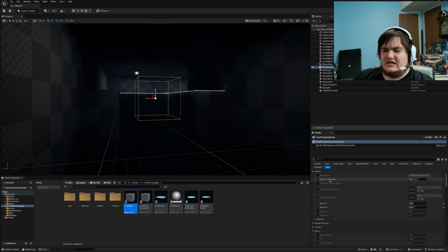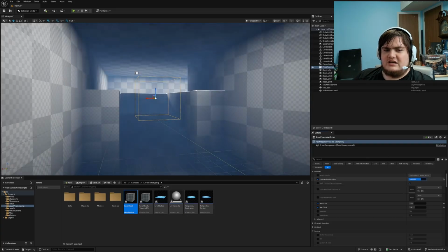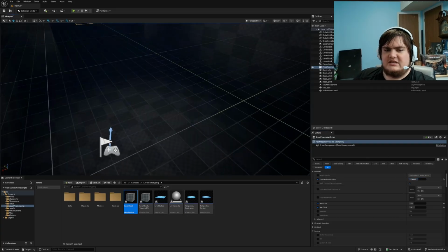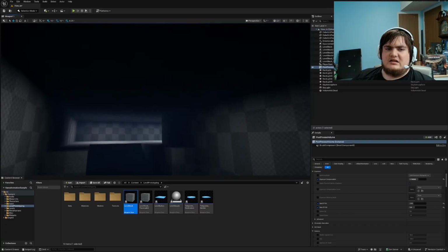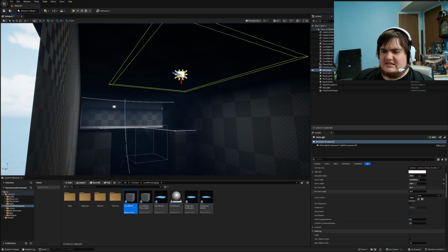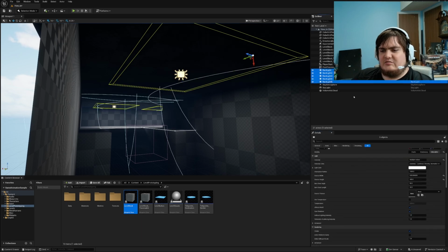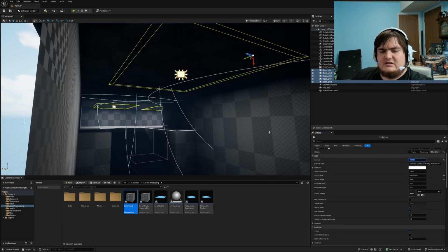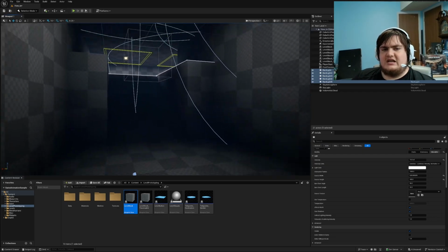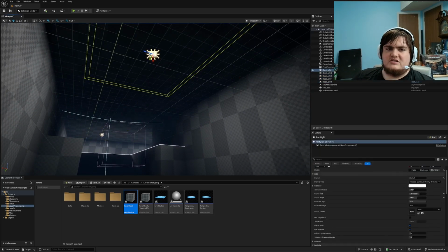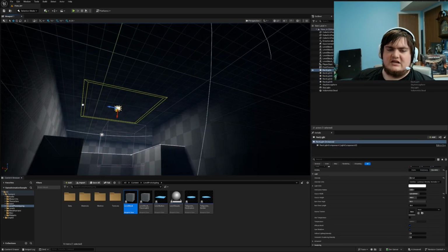And then I can also use exposure control right here, I can raise it up a little bit and get some of that light back. Now it's really just controlling it with my lights in here. So if I set all of these to 10, I get a much better setup. I'm going to go with 15 actually. So there we go. Now we're not as super high dense fog as we were before. So if I slide this forward, we can see this ramp.